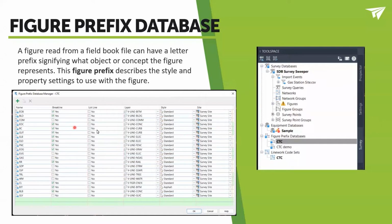Here in the lower left-hand side is our figure prefix database manager. Now we have a few codes here. It gives you options to enter codes as well as enter if they are going to be break lines. Break lines are going to be figures, and we can enter those into our surfaces, and how we're going to create our surface, as well as our point groups. This gives us an automation of how they are going to be stringed together, which saves us some time.